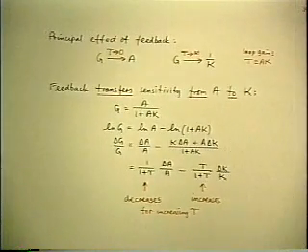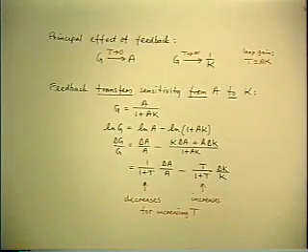Here's another basic property of feedback. It's commonly said that feedback reduces the sensitivity of the closed-loop gain to variations in the internal parameters. That is, if you have a certain tolerance on a component, say 10%, you put a feedback loop around it, you will get less than a 10% variation in the resulting gain. That's one of the important reasons for using feedback. So that's a common statement. Feedback reduces sensitivity to the variations of the internal components. That's only partially true.